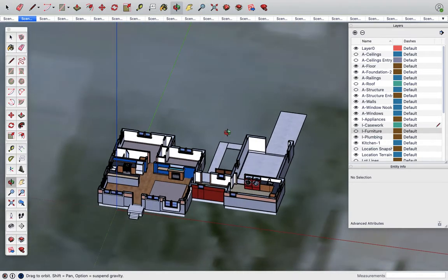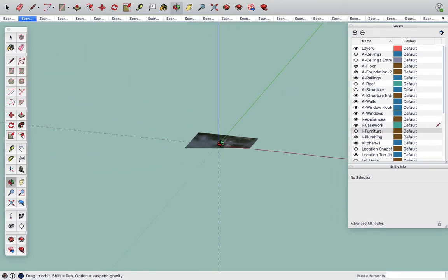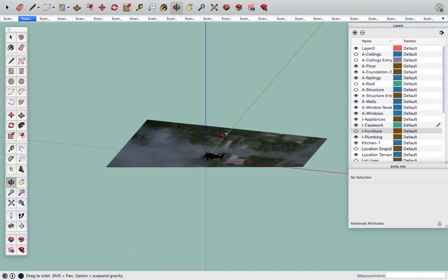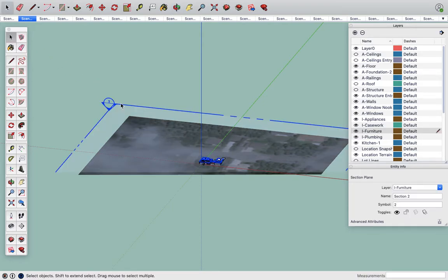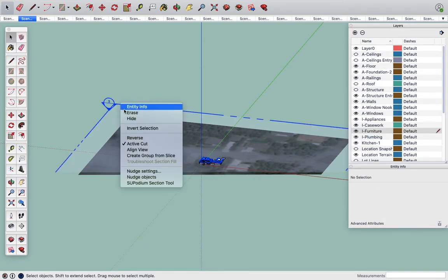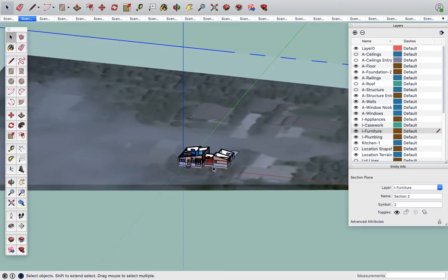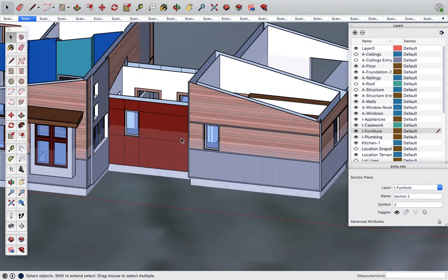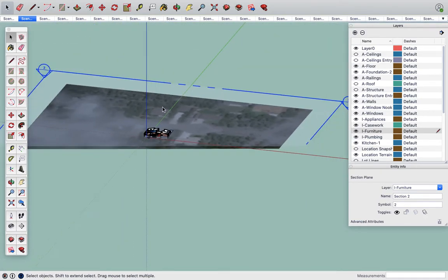If you want to do a building section, there's two things you can do with this. You can either, oh, I know. Now I can't see the furniture layer because my section cut is on that layer. I can either right click on this and make it a non-active cut, which kind of grays it out, and it's not there anymore, but you kind of see it grayed out. But I think that gets confusing. You have too much mess in your drawing.